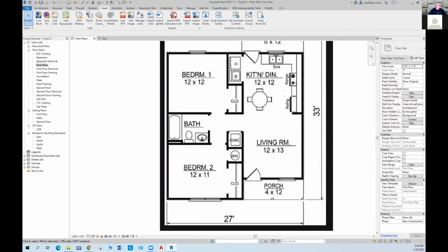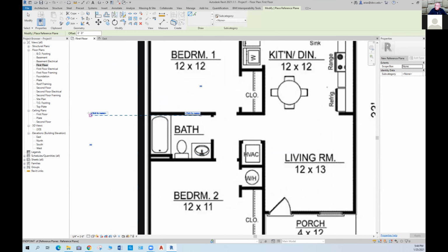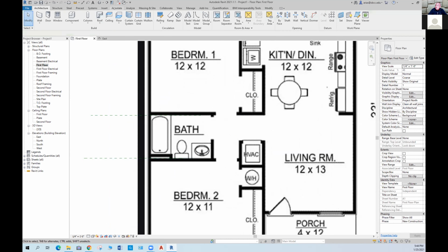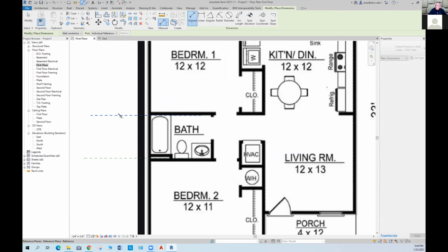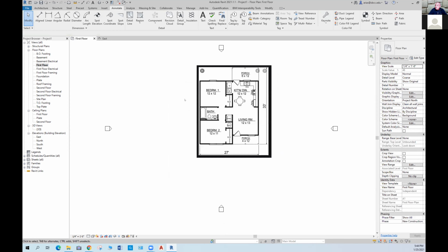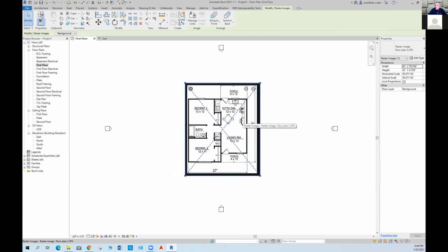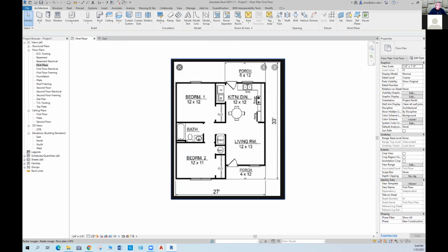And let's just check to see if it got scaled correctly. This should be about 5 feet here in the inside of the bathroom. So annotate, linear, aligned, and 5/6. So that's great. So it seems to be okay. So next step, remember, once we annotate that, I'm going to move this down a bit, center, and I am going to lock the image by clicking on the image and then select lock or pin, I'm sorry. And now I'm ready to create walls.